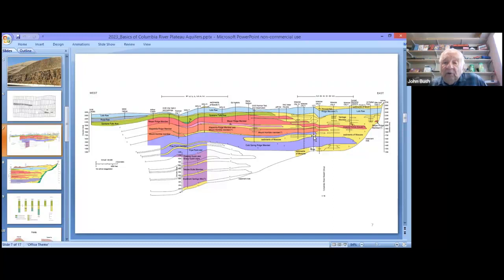The inner bed here where the cursor is at is cased off. Only a small portion right in the middle of this thick basalt flow has some openings. And then you have a screen at the bottom. The screen is, like in this case, a stainless steel screen that's welded onto the bottom of the casing that allows water in. So it cased off all the sediments except the bottom. So we got water coming in from the sediments.